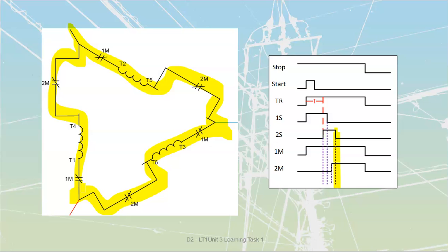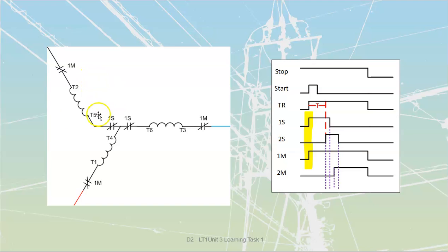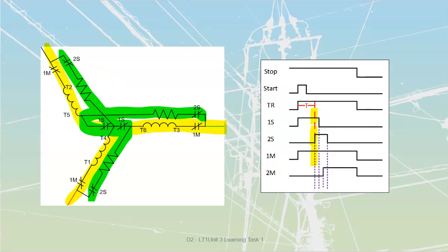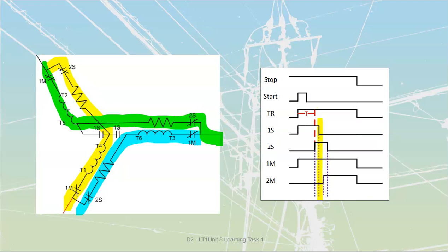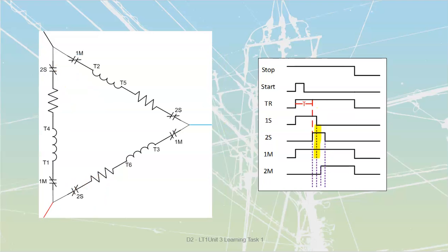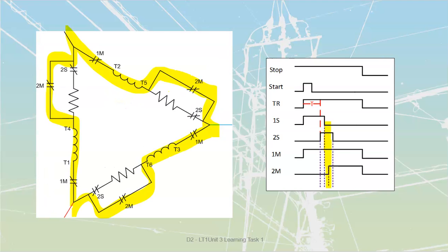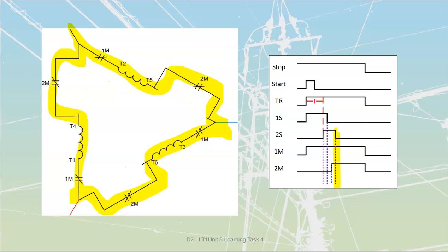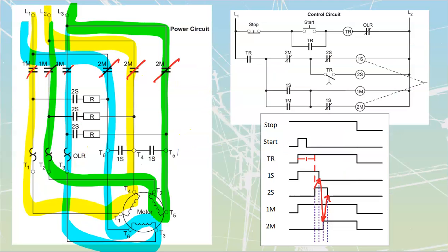It's a pretty cool system, really, when you take a look at it, watching the way that this transitions all the way through, where we start this thing up in a Y, and then maybe build a parallel resistance Y, and then we transition over into a series RL type of circuit just for a split second, and then we short around the resistance, and then we remove the resistance altogether by opening up that one set of contacts. It's a lovely but insanely complicated setup that we are going through here as we're moving from one set of contacts to the other.